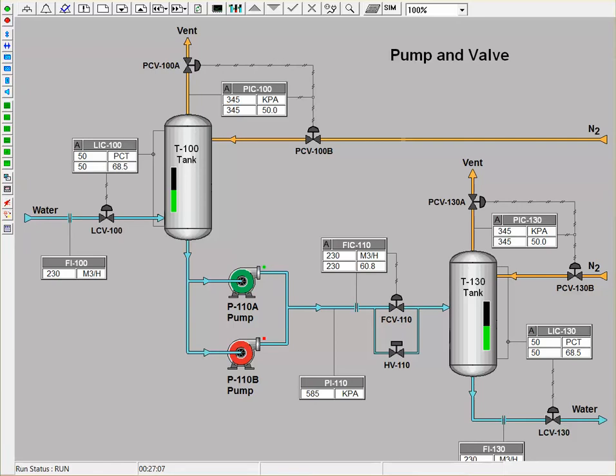If we want the level to be 52% full, we will notice that the percent output of the valve will increase, and it will do so until the level process variable meets the set point variable of 52. Once this is reached, the output can be maintained at that particular output if the valve is put into manual.